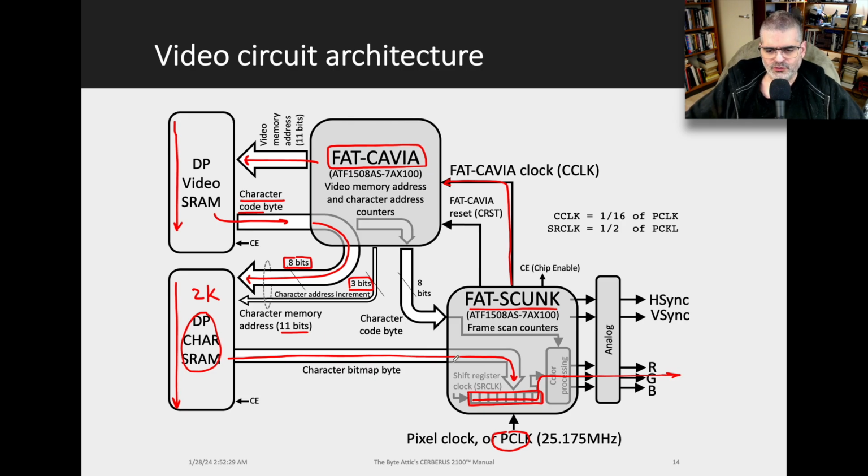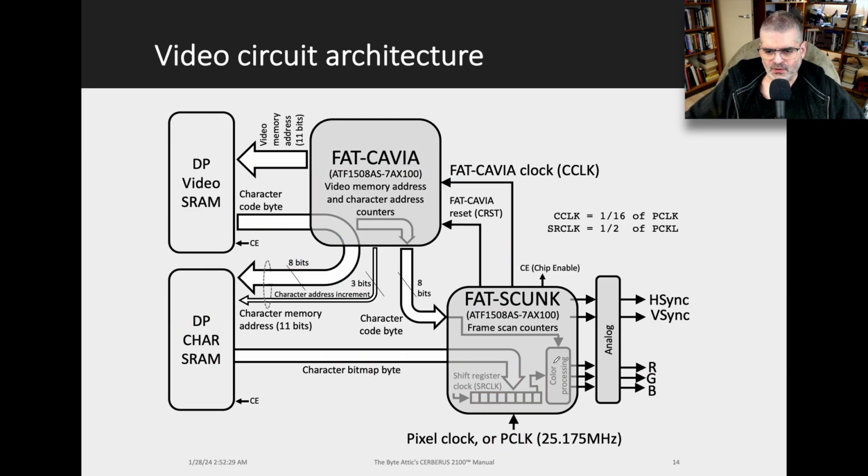All right, what else do we need to do? Well, we have color processing. How do we decide with which color to print the ones here in the shift register? Suppose this is 0, 0, 1, 0, 0. When you're spitting out a 0, well, that's the background color. It's black in all cases. But when you're spitting out a 1, we need to know which color to use.